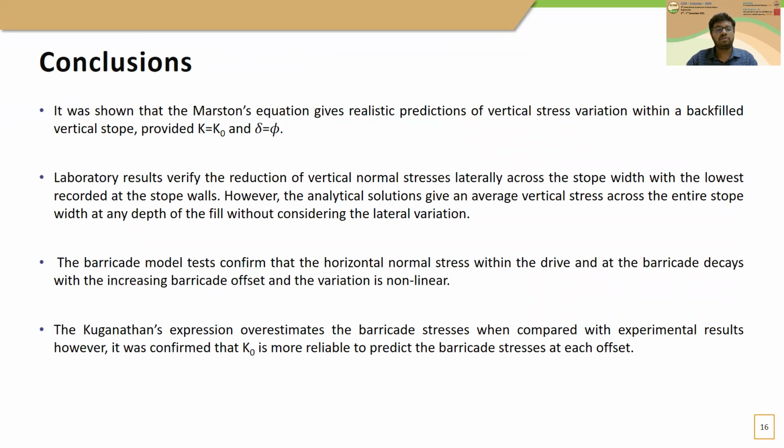Here are the key conclusions from the research. According to that, it was shown that Marston's equation gives realistic predictions of vertical stress variation within a backfill stope, provided K equals K0 and delta equals 5.